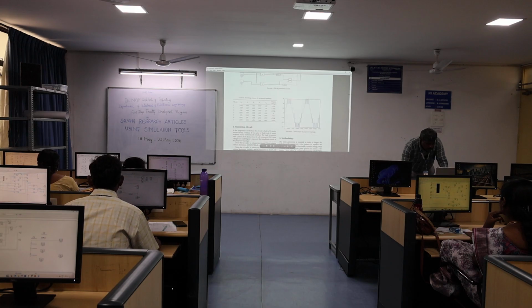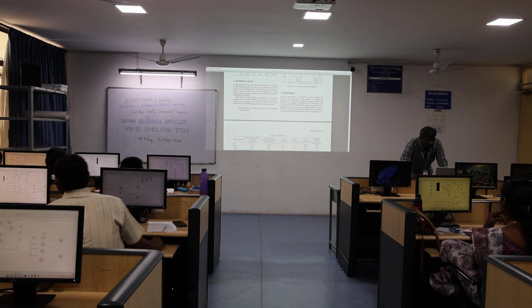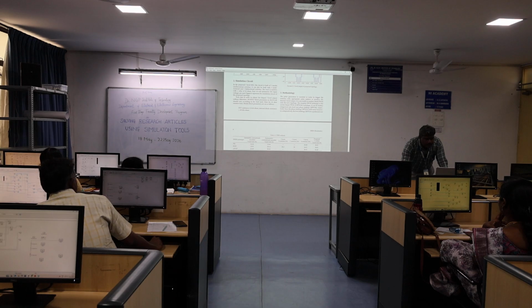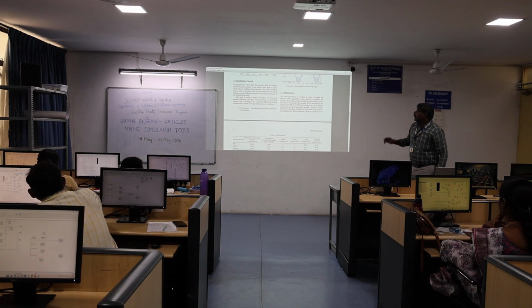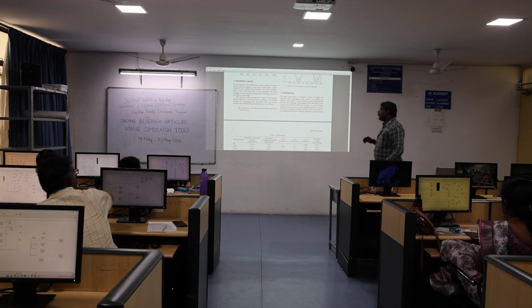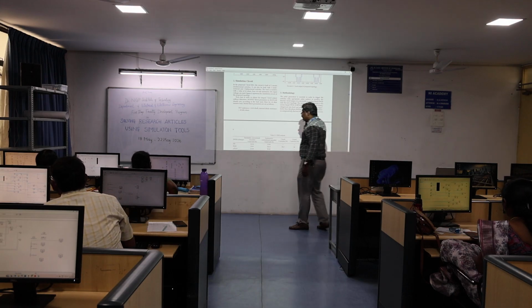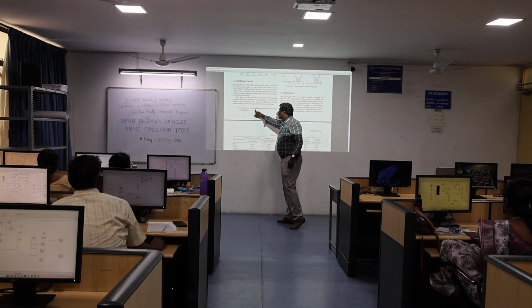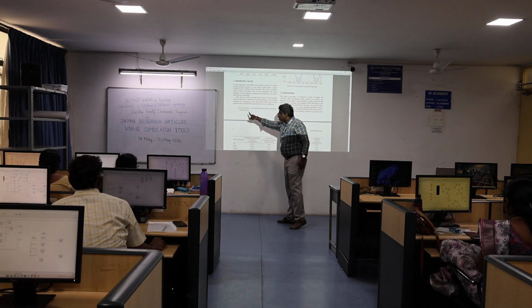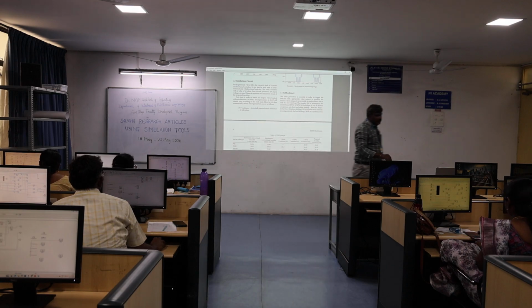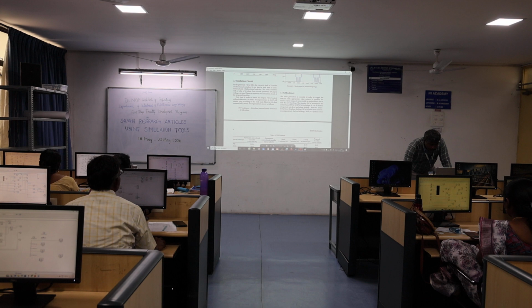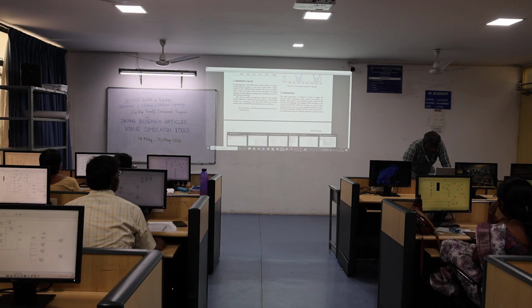Okay, next one more thing. Before going to the simulation, in the paper itself they mention some MOSFET internal parameter values. The FET resistance value is 0.01, and the internal diode resistance value is 10 kilo ohm. You have to change the internal values of the MOSFET. So here 10 ohm for the load value.